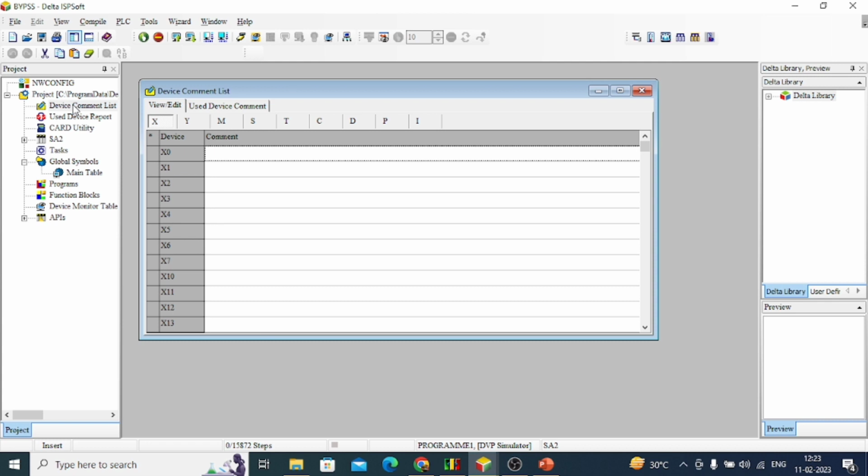After that we need to check whether the cutting component is present or not. For that we need one sensor. For interfacing that sensor we need one input, that is x1. And if the cutting component is present, we need to cut that component. For that we need one output, that is the cutting machine, that is y0. Then if the sensor is malfunctioned or failed, we need to bypass that sensor. For that we need another input, that is x2.